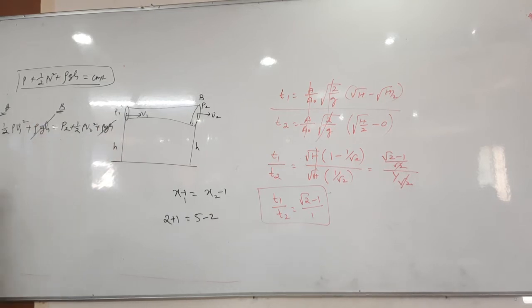Now you get P1 plus half rho V1 square equals P2 plus half rho V2 square. From this what I can say? The sum of the pressure energy and kinetic energy per volume is always constant. That one you already know, we have done so many problems based on that also. But the thing is here, whenever P1 has more value, at that time how should V1 be? For example, if V1 is also more, then what happens? Everything on this side is more, it cannot be balanced here.